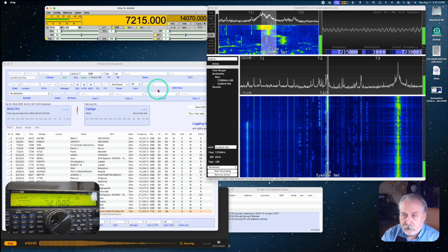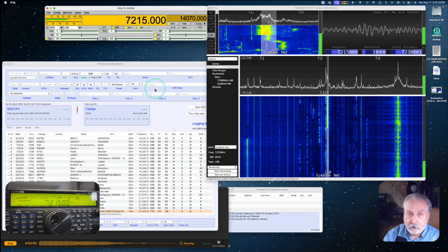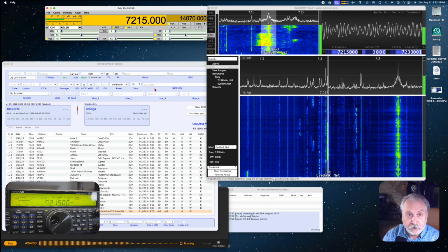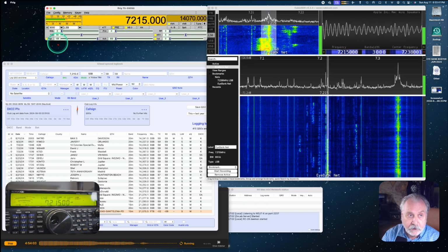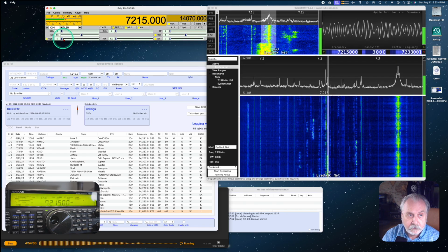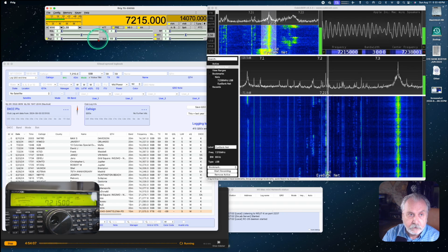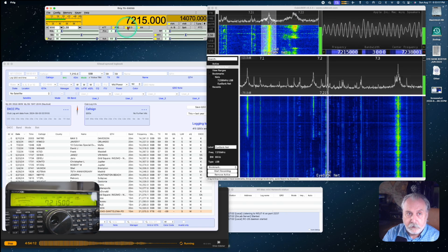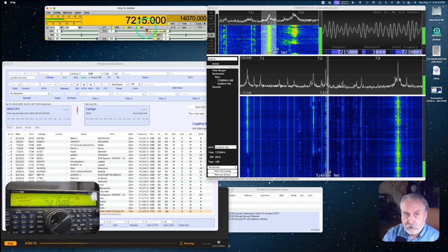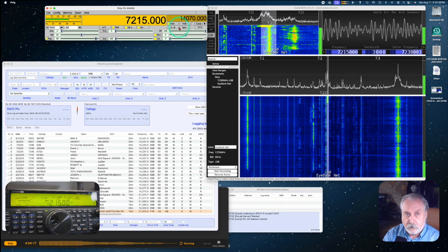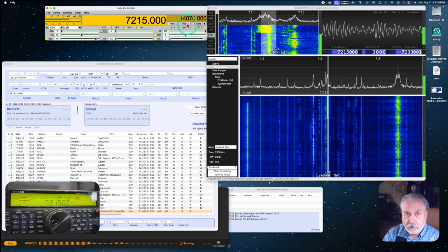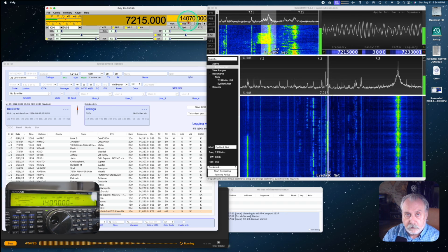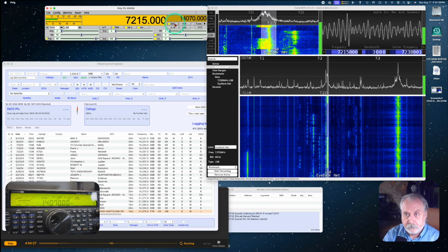So I don't have as many controls as I did with the Kenwood software, but a lot of them I don't need to use all the time. I set them in the menus on the radio and pretty much leave them alone. The main things I have on here is for my power measure control. And I also have my preamp, my noise blanking, the auto notch is turned on. What VFO control I want, I'm on VFOA. I can switch to B if I want to. I'll do that real quick just to show you that it's highlighted.